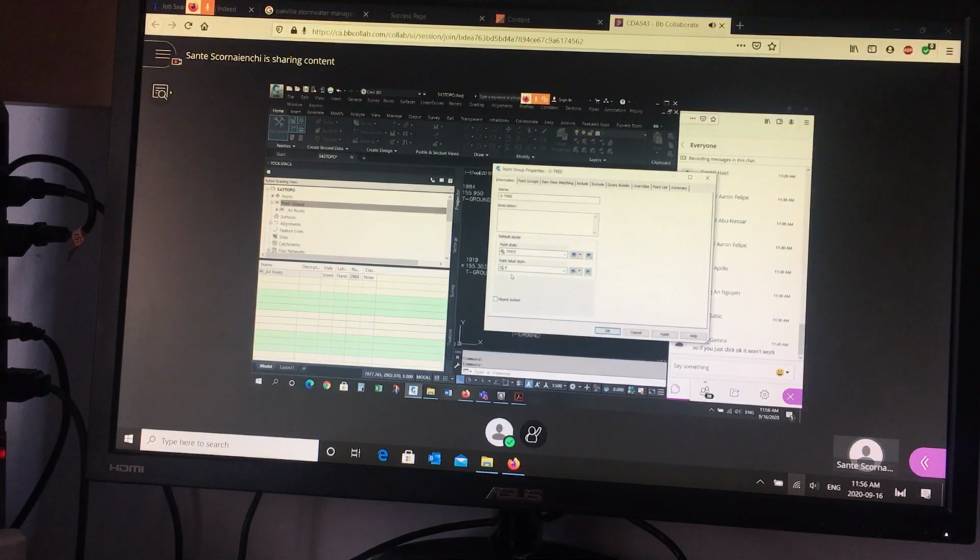And that's why it's important that the actual individual objects in the drawing are set to default. A better word would be by group. Remember with the layer, by color, by group, by layer for color, and by layer for line type. A better word instead of default is by group. What's your style? By the group member, and so on.